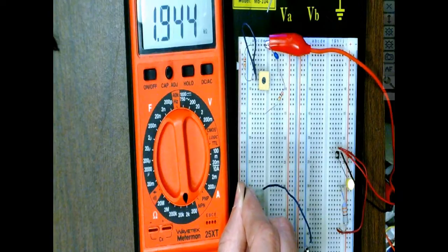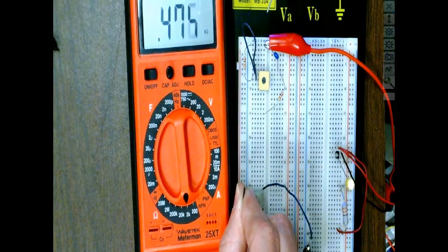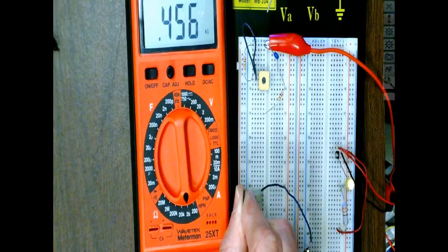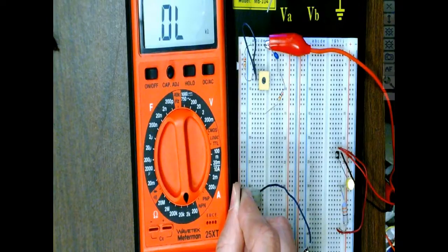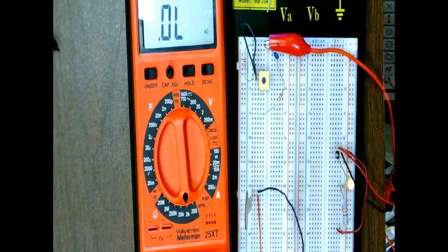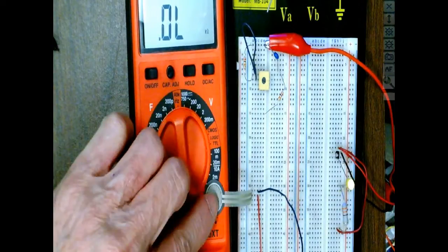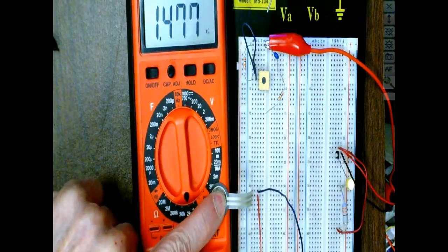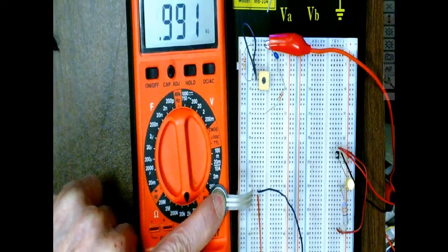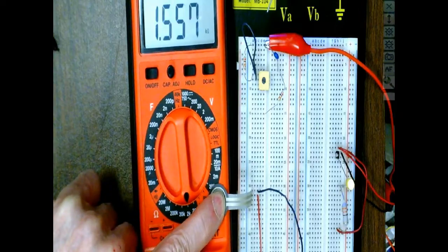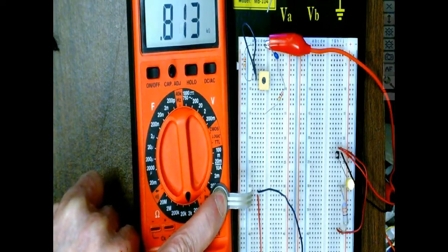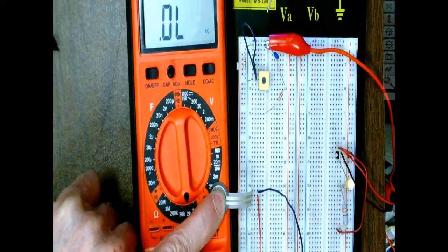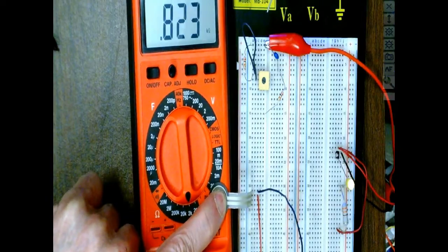I'm going to try to vary my pressure a little bit. So the tighter I squeeze on this, notice the resistance goes down. The less I squeeze on it, the resistance goes up. So this is a pressure sensor. It's sensing the pressure that I'm applying to it. Okay, so I'll put it on top of my meter, and all I'm doing is just pressing down on it. The resistance goes down, and when I release some of it, the resistance goes up. This guy responds really, really fast, too. It's a pretty good pressure sensor.